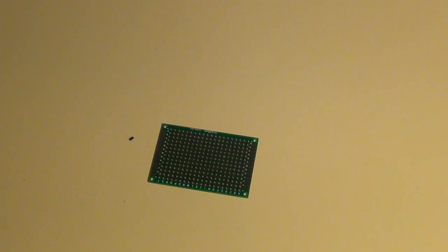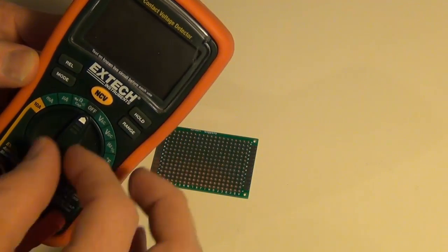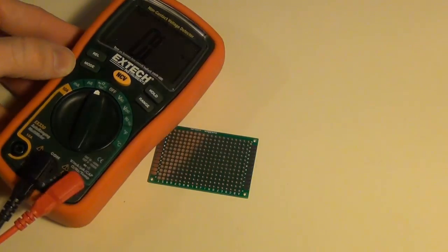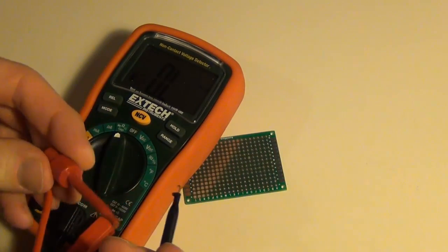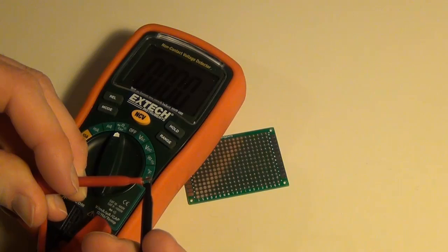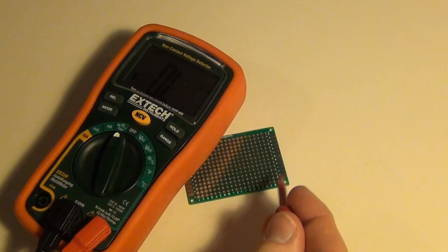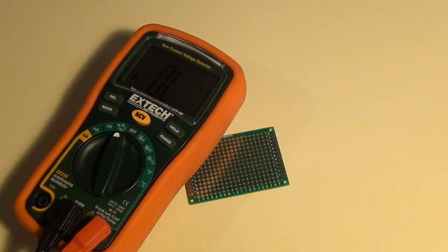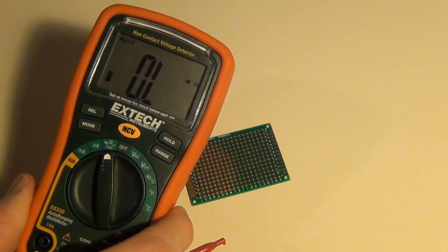So one of the things that I find is very useful for troubleshooting when you're doing smaller projects and soldering is a good multimeter like this. So I can just set it over to the ohm setting, and then I can check my connections. If you've never done this, I'm sure there's plenty of videos, but just a basic overview here. When I touch these two connections together, it'll change to 4 zeros and show that it's a connection. So I can quickly test my parts that I solder on this prototyping board here to make sure that my connections are good. So if you don't have one, I highly recommend a good multimeter to test with.